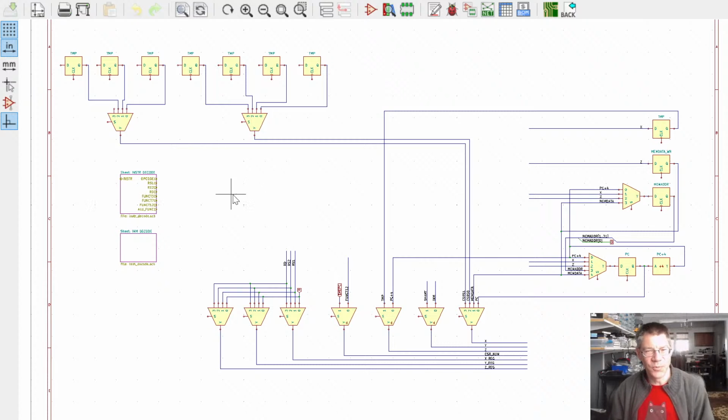I did kind of want to get started with the sequencer card first, just to see what things would look like, and to get started on a little more interesting circuitry. The other thing is that you can see we've got these basic modules here. So we've got like a 4-input 32-bit multiplexer. So if I can build a little module that is a 4-input 32-bit module, maybe I could just build a bunch of them and maybe stick cards or something like that. Yeah, the shifter is definitely a bunch of buffers.